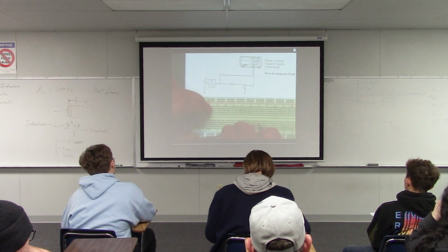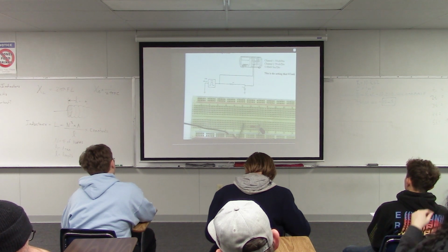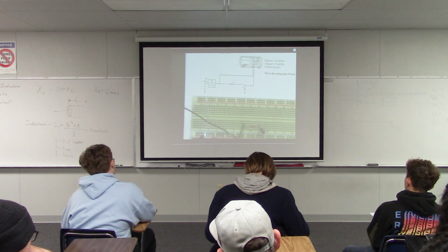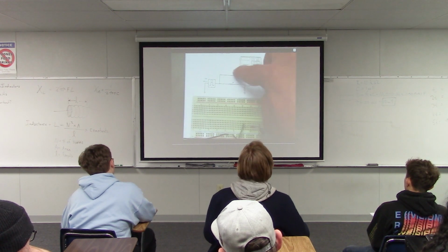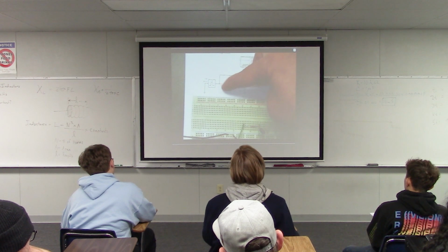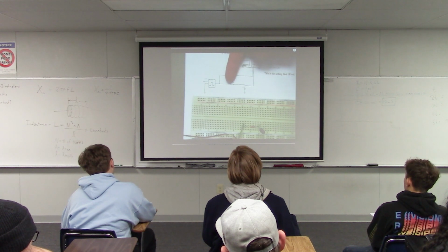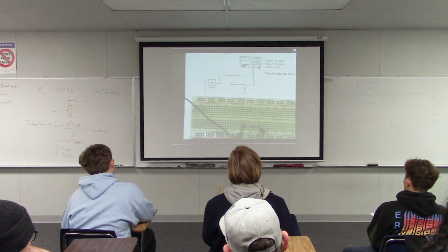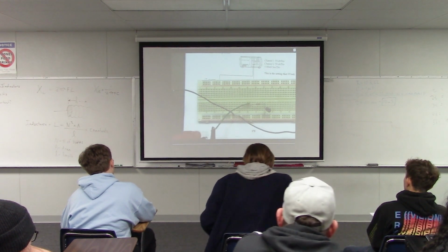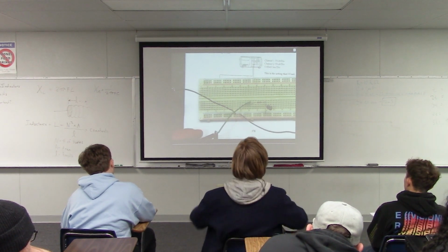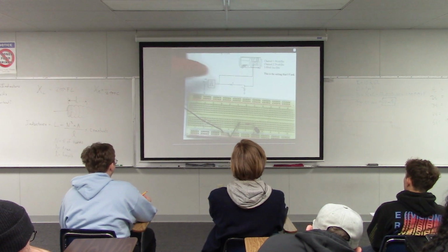I'm going to push that into the ground row, and then I'm going to connect the other lead from this oscilloscope, the probe. I'm going to hook that right here where the function generator connects to the resistor. Okay, so I've already got a jumper wire going in right here, so I'm going to connect my oscilloscope right to that jumper wire. That's the same jumper wire that has the signal from the function generator.